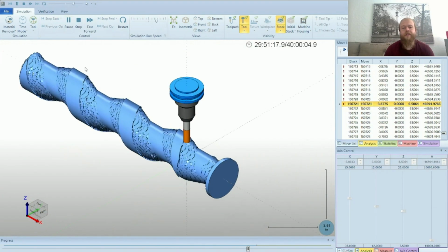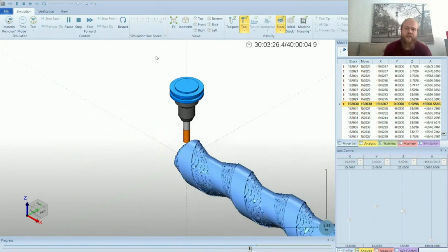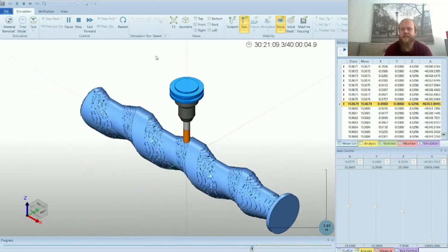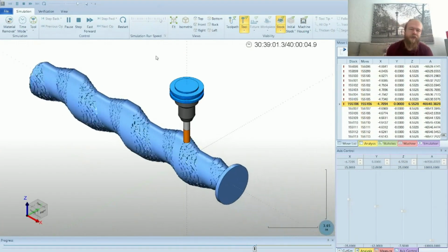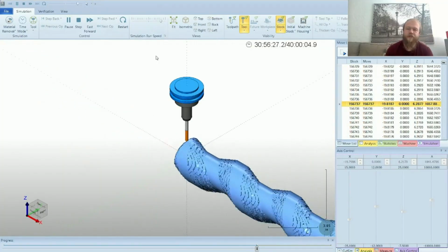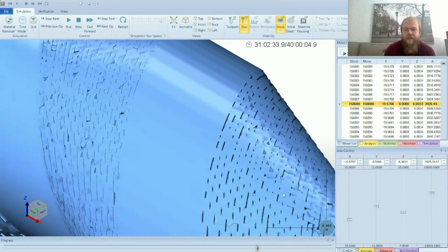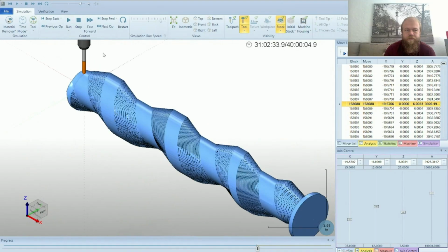And that's also found in the 3-axis roughing. So sort of like a semi-finish operation, or an interim type of milling operation between the roughing and the finish toolpath. You use your roughing to do an extra couple of steps to have a lot less material to cover for the finish operation here.